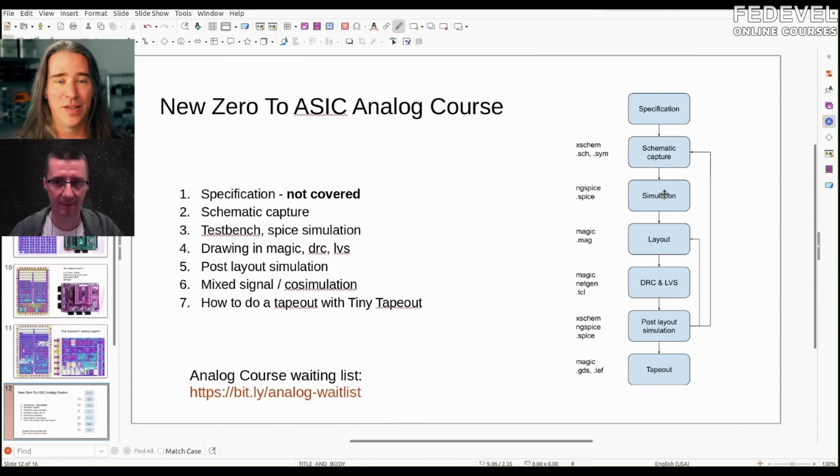I actually spoke recently to Tim Edwards, who maintains Magic, and he was like, yeah, it'll give you the capacitance between a metal layer and the substrate. And this is related to the size of the metal layer, but also how far it is and everything. So when you do parasitic extraction, what you're doing is extracting the circuit, how you wired it up, but also all those parasitics, all that R, that C that's everywhere. And then you did that simulation, you did your layout. This is down here, you're doing post layout simulation. That is where you compare, okay, in real life, well, as close as we're going to get on a computer, how good is this circuit?